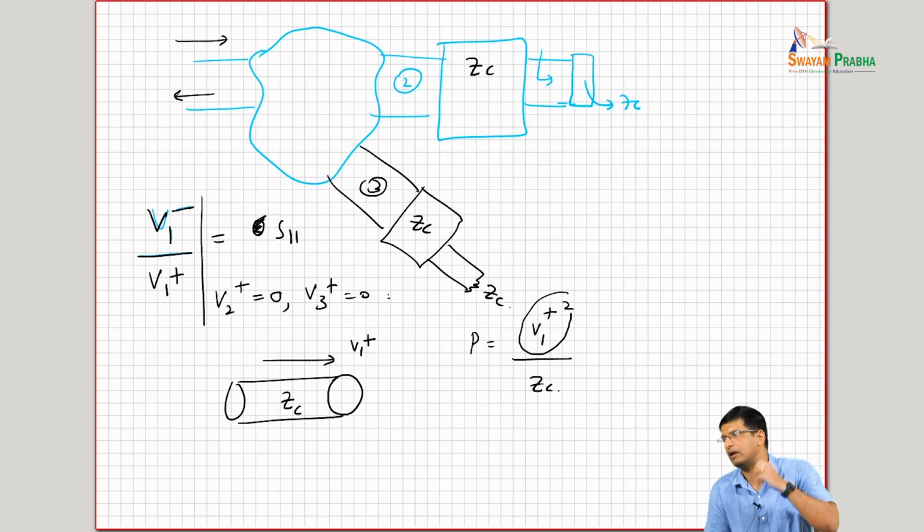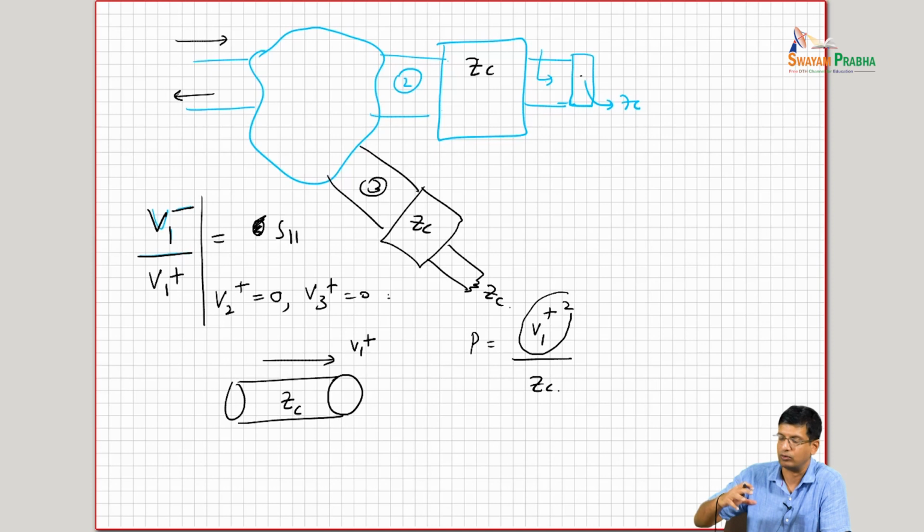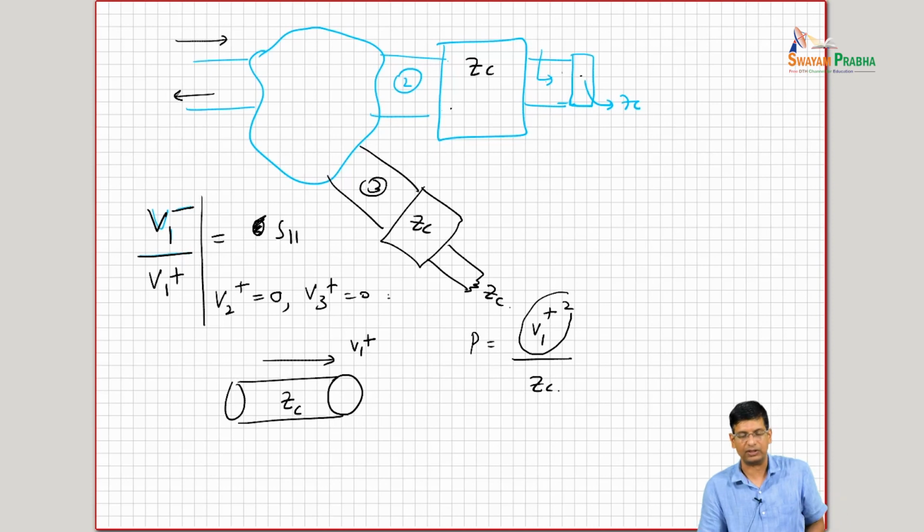So you can think as power going into your network and power getting reflected back from your network. And what you do when you put a termination here which is matched to the impedance is that you are absorbing the power, so none of the power is reflected back, right? So making S parameter measurements is a lot easier at high frequencies than Z parameters, right?